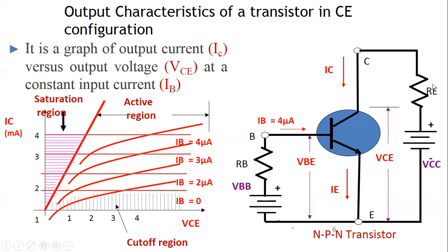Similarly with voltage: whatever voltage we get as output with respect to input, we can say the voltage is increased, but by how much? It is output voltage upon input voltage, and that ratio gives the amount by which the output is increased. Output upon input voltage, similarly output current upon input current. This is the gain, meaning the extra that the output circuit is going to deliver. IB times some value is going to be IC. So IC upon IB, that much is the gain.